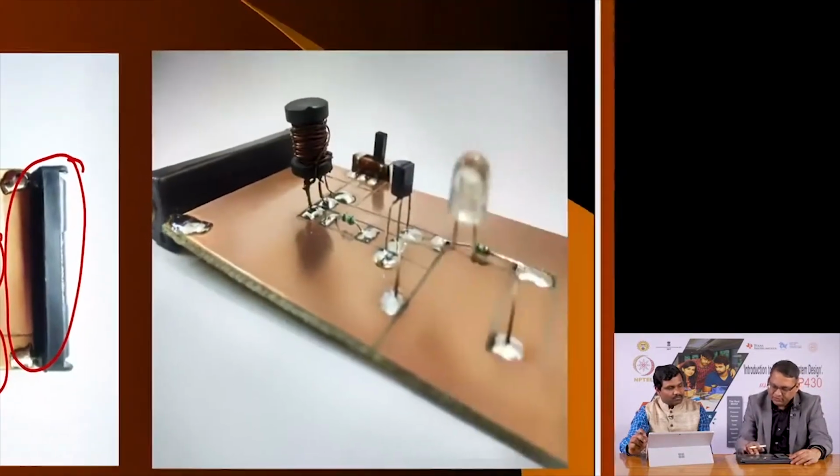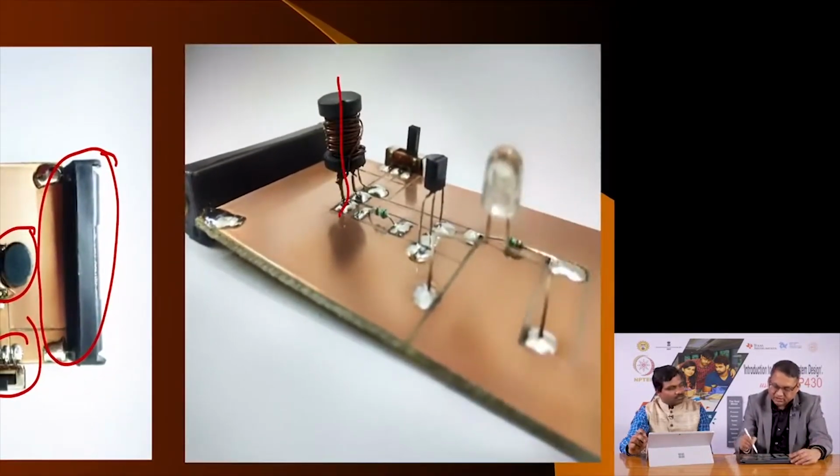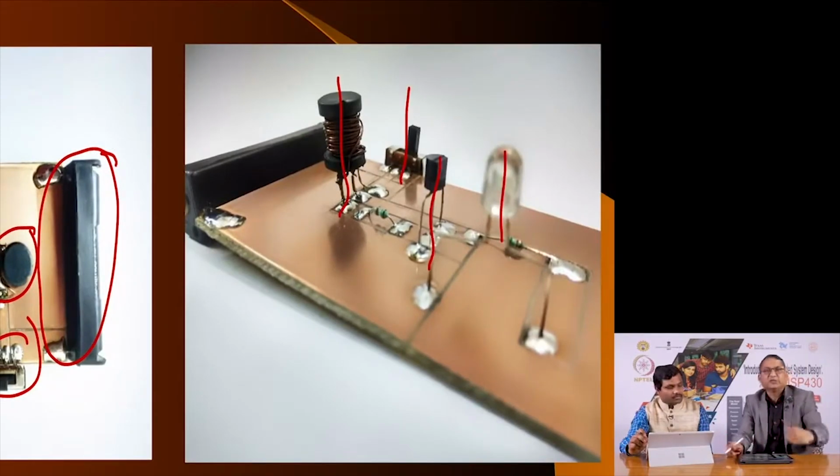Here is another view. As you see here, these components are rising up in the air. This is a very simple circuit, but imagine that there are 50, 100 components like this, you will suddenly see these components as tall buildings, and this is the reason why this technique of prototyping a circuit is called Manhattan style. This is very popular whenever you use high frequency circuits.